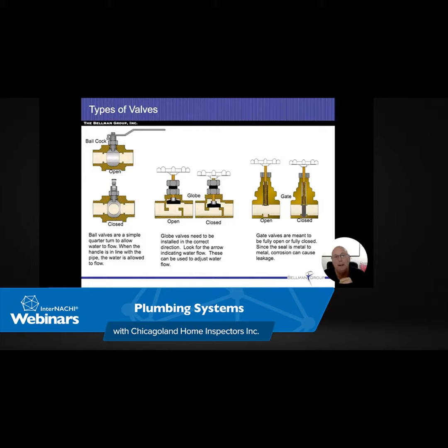Then he would turn the pressure tank on and off real fast, basically creating a bunch of water hammers inside the pipe, trying to knock a whole bunch of this stuff loose. From what he tells me, it works. The pressure would go down, and then he would bang these things up a lot, and it would free up, and everybody would be happy for a while.